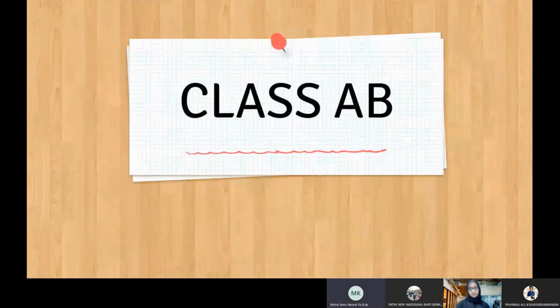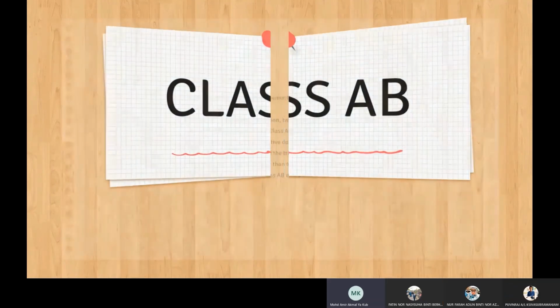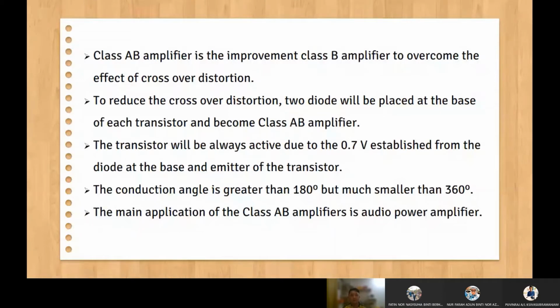Alright. For the class AB amplifier. Class AB amplifier is basically an improvement of the class B amplifier to overcome the effect of crossover distortion. To reduce the crossover distortion, we will place two diodes at the base of each transistor and it will become a class AB amplifier. The conduction angle is greater than 180 degrees but much smaller than 360 degrees.